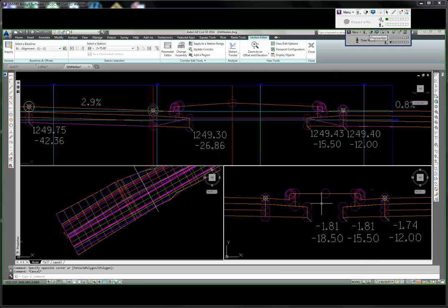First, I turned off my updates. I created a generic link from this point over here to put an anchor point here. I put my marked point on that anchor point. That has to happen before I place the median tool itself, or else it doesn't see it and doesn't react to it. I put that median point in with the name of RT because I knew my median tool automatically defaulted to RT. You can name it whatever you want as long as they're in agreement.